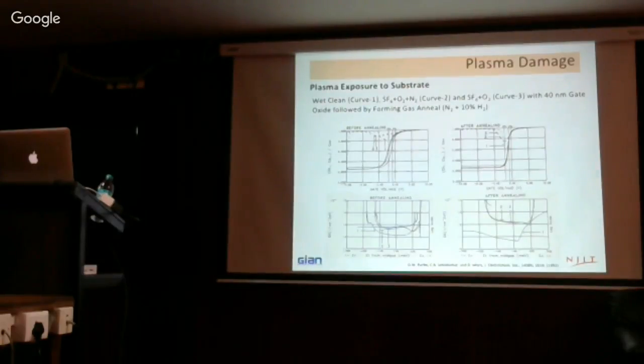That is because there is a series resistance. That series resistance I mentioned: if the series resistance is extremely high, once you change the frequency, the capacitance itself will change, the accumulation capacitance will change. That is due to the series resistance. So you can see that there is a variation of the accumulation capacitance as a function of frequency. That is called the frequency dispersion. So that is very standard if you have series resistance.